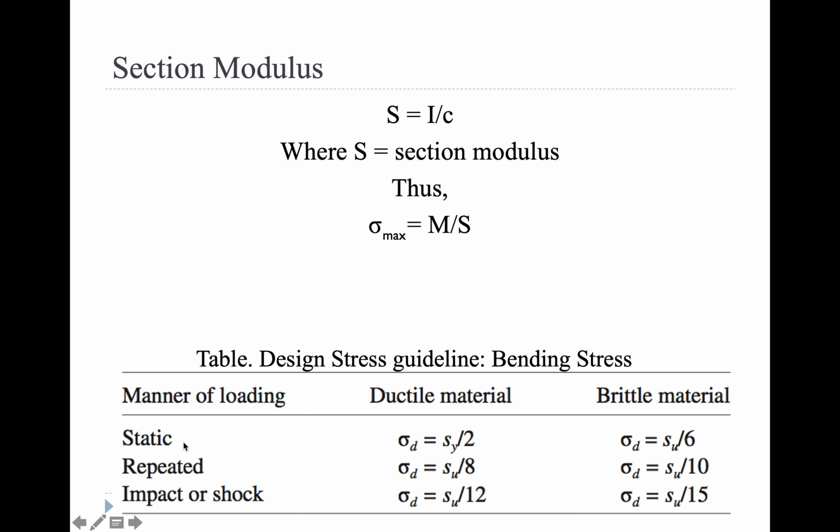Well, what if you constantly repeat it? That's the second one. What if I repeat the load? I add 100 pounds, I take it off. I add 100 pounds, I take it off. It's like the material is working out, right? It constantly has that. The last one is an impact or shock. What if you drop something on it? This is like dropping your phone and how the phone case and the screen resist the impact or shock. It's just one time, and that's it.